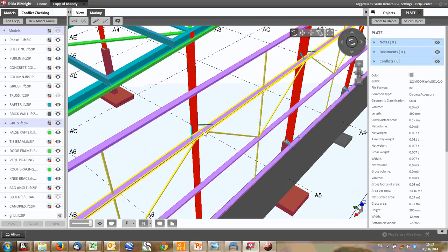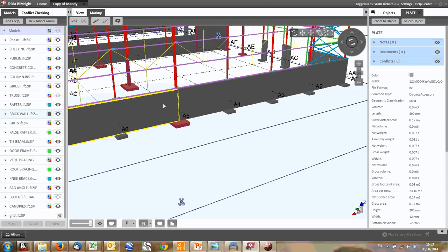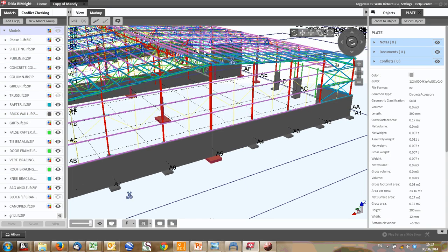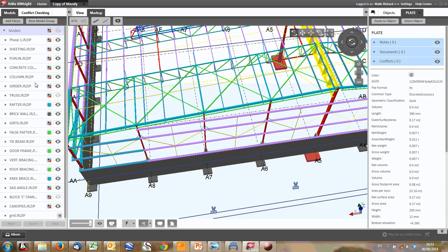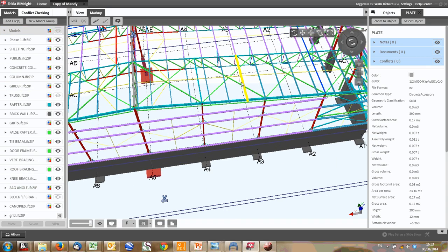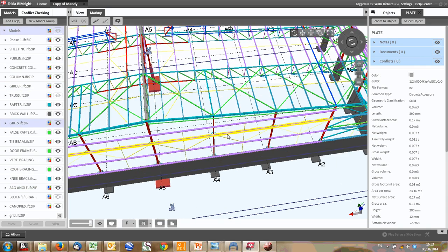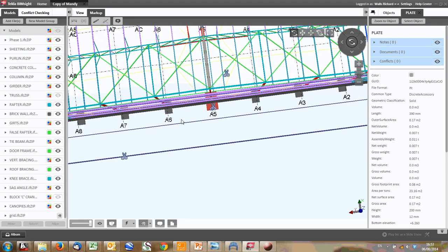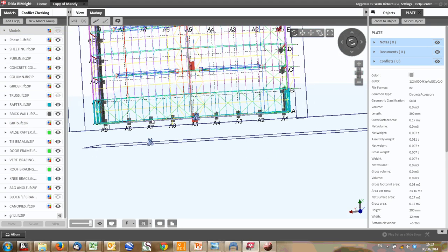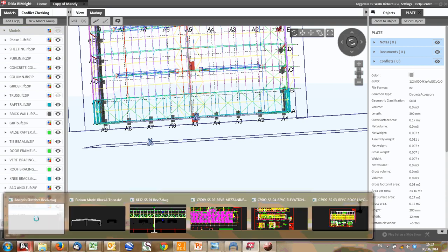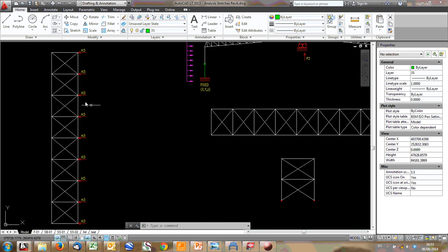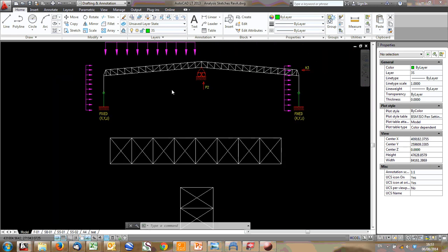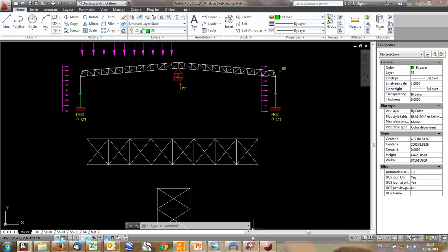Now, let's have a look at the top. Where does this top load go? So the wind comes along horizontally. We need to get this load now into these foundations. And the way we do that is with roof bracing. We can provide a lot of stiffness to this entire gable face with roof bracing, whereby a load coming along hits it, and this is a giant truss all the way along the top. So if we go back to our model, there we go, a giant brace all the way along the top. In the same way that we brace the trusses, we're bracing our gable face.